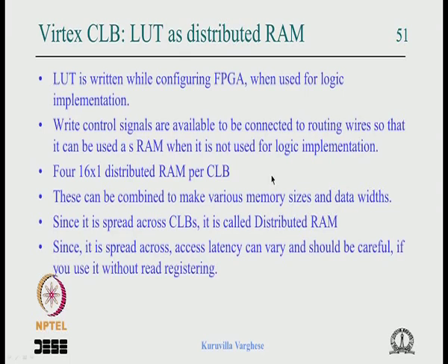Suppose, for example, you are trying to generate a waveform by lookup table. Then in waveform generation you will store the samples and output them at regular intervals, and if the read access of the memory is variable, then there will be jitter and distortion in the waveform. So you might not think about it, but this could be the result.